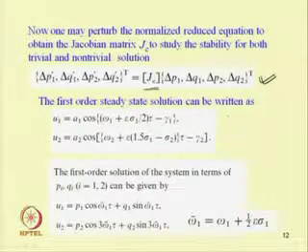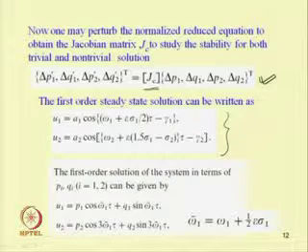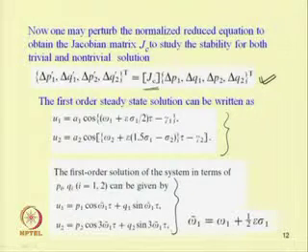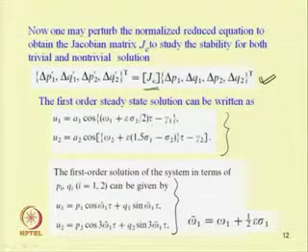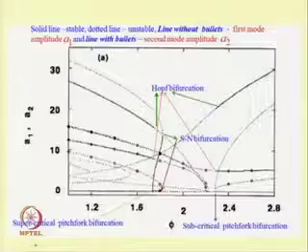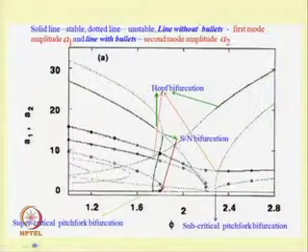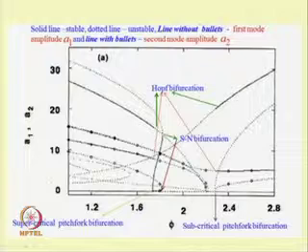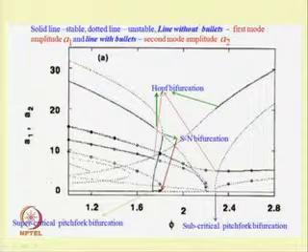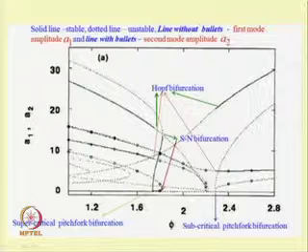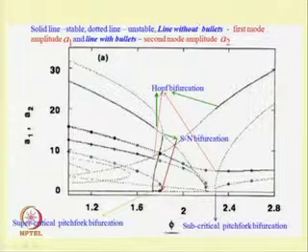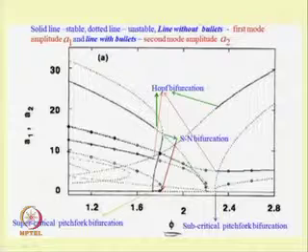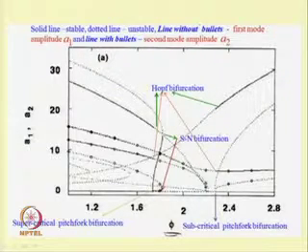So, in this case we have 4 equations. The objective of this lecture is to show what numerical techniques we will use to solve these 4 equations. Here one can use Newton's method. This is the frequency response curve, in which both A1 and A2 are plotted with respect to the forcing frequency phi, and phi is nearly equal to 2.